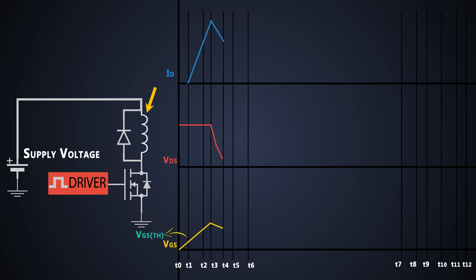Let's say the load here has a low resistance. In this case, a very large amount of drain current will flow. The change in commutation of the freewheel diode also increases, which might generate a high reverse recovery current through the diode, which reaches the maximum value and then decreases suddenly. Due to this, excessive voltage may build up within the circuit, which eventually results in over-voltage breakdown. So this change in voltage with respect to time has a very adverse effect on the MOSFET, which is called the dV/dt rate of the MOSFET switching, which we will see in future video topics.